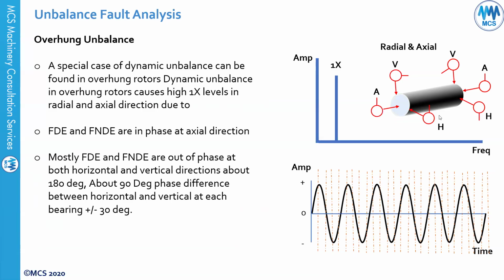As for the relationship between horizontal and vertical vibration, horizontal could be double or maximum triple the vertical to say we have imbalance. If it's 4 times or 5 times higher in horizontal than vertical, this could be an indication of structure looseness, which is a result of high flexibility in the structure or lower stiffness, which needs to be adjusted by stiffening supports or doing some modification to the structure itself.